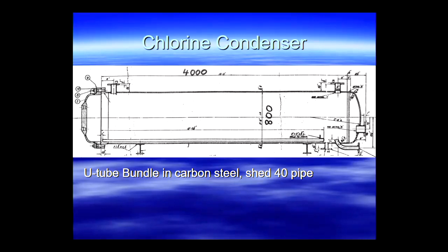Oh, we've got this thing corroding. It corrodes all the time. I said, why is it corroding? Oh, we don't know. I said, but chlorine gas should be absolutely non-corrosive to steel, it has no effect whatsoever. You can hold chlorine gas in carbon steel vessels and it never ever corrodes. Unless the temperature gets to 150, then you get a pyrophoric reaction, which is another matter. But here we're not talking about that, we're talking about sub-zero temperatures. At these temperatures and conditions, the chlorine should not be corrosive at all.